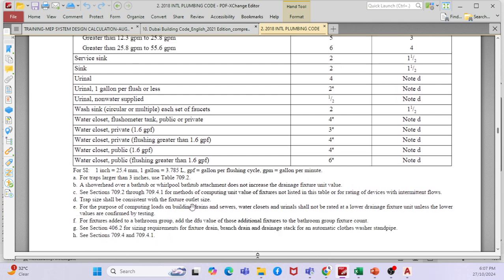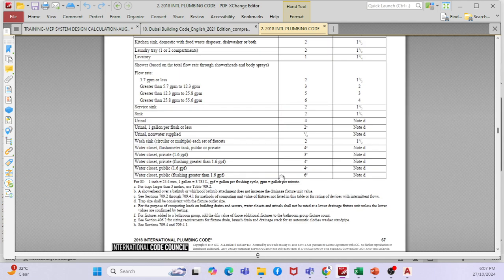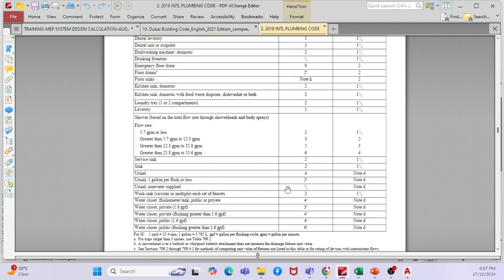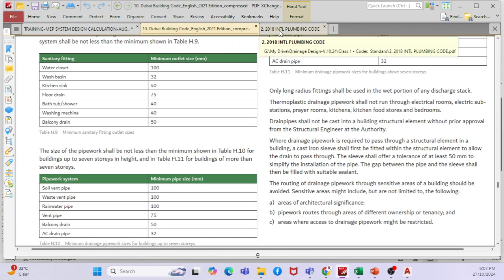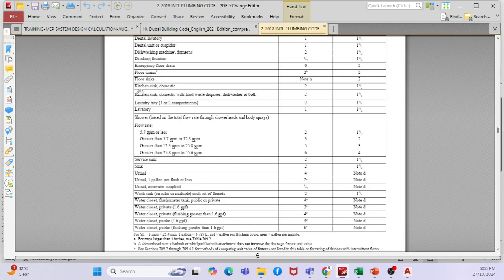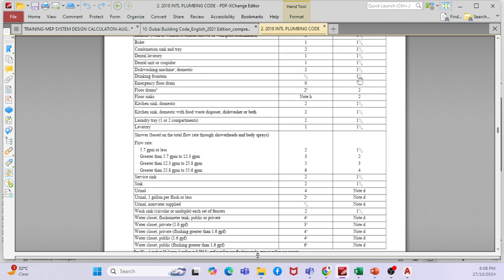I have one question. Yeah, yeah. While pipe sizing of floor drain, usually 75 mm, we take 75 mm from the outlet. Okay, and after how many branch connections will the 75 mm convert to 110? Yeah. See, that is what you have, a floor drain. What is the DFU value? 2, right? 2 is the value.